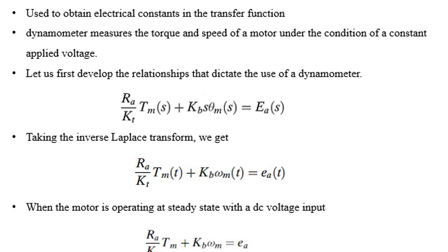Dear students, we have studied various constants used in transfer function. Now we will study how to find values of these constants with the help of dynamometer test. For this test, we use torque and speed of a motor under the condition of constant applied voltage.